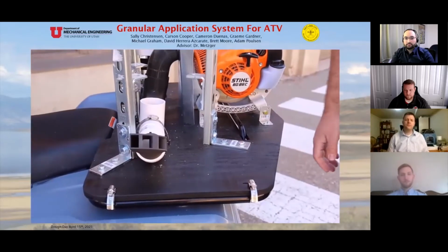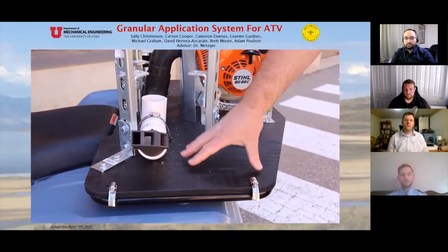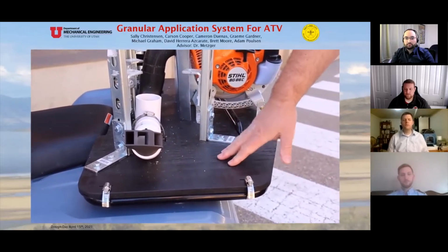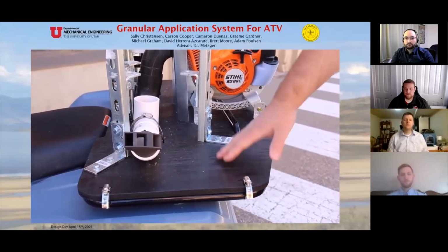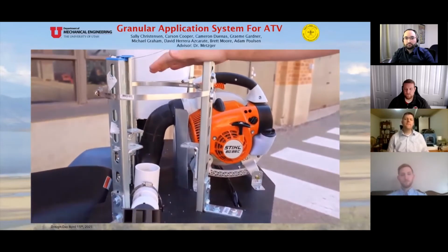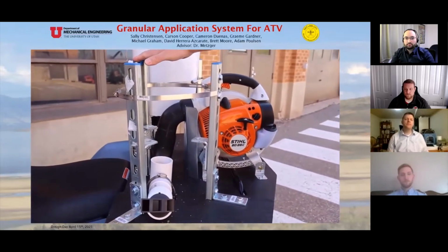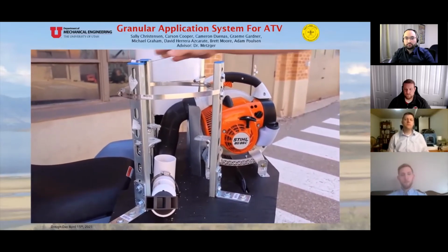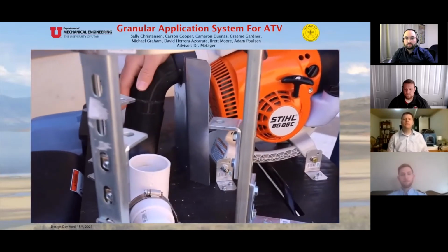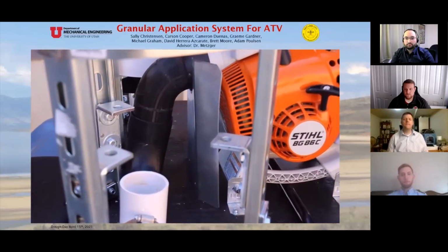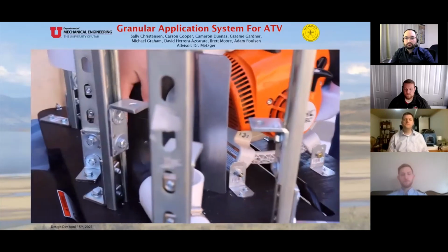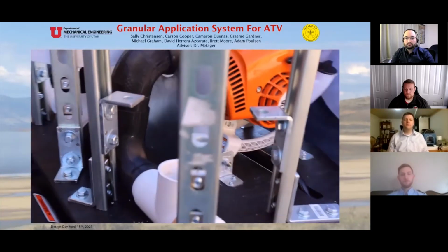The entire system is mounted to a piece of CNC'd plywood, which is coated in truck bed liner to protect it from fuel and water. The hoppers are mounted securely to the base with galvanized unistrut, which is corrosion resistant and very sturdy. To protect the rider and the system from exhaust fumes and heat, a metal shield is installed between the duct and the exhaust.